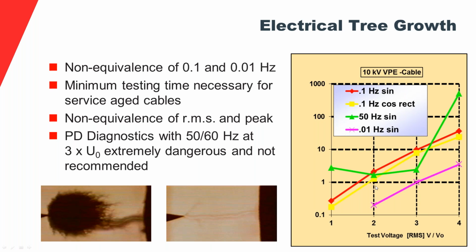And again, then you're not doing really a proper withstand test, a demanding stress test to the insulation. And just to clarify this, this study here is one of the base scientific documents of the IEC standard. These values are all in RMS, so this means 3 times U0 RMS. And then over here, I found 2 pictures that show what the difference is when you have 50 hertz. You have this tumbleweed kind of treeing, and the VLF channel mechanism. So right, it's VLF.